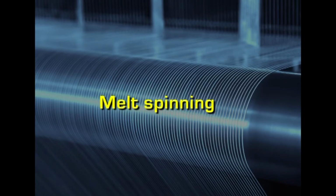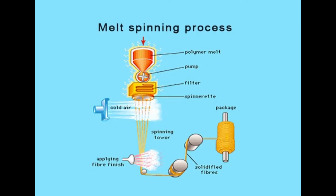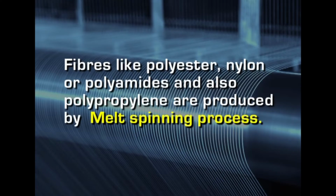Coming to melt spinning, this is the simplest method, because it involves only melting the polymer, extruding it through the spinneret, and then cooling it in air. When it hits the air, it gets cooled and solidifies in the form of a very thin filament. It is also very inexpensive, because we are not using any solvent, and solvent recovery is not required in this method. So this is the most inexpensive method, and fibers like polyester, nylon or polyamides and also polypropylene are produced by this melt spinning process.